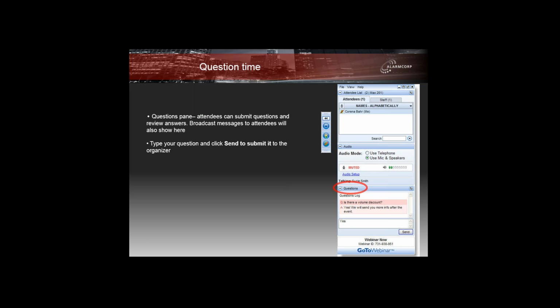Without that box, you're going to have to come up with your own tamper-secure box to mount directly next to the seismic in order for it to be approved. So in this case, you can just stick the GMT4 box on the wall, put the seismic in, run your cable to it via conduit or through the wall into the back of the box, and you've got now a fully secure, approved installation.